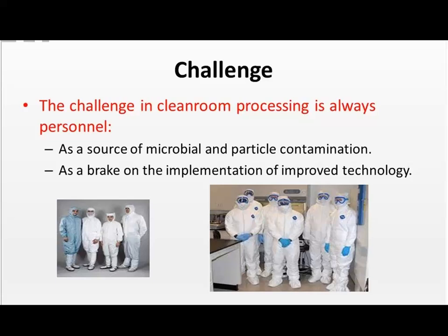When you're in an aseptic environment, movement is critical. You want to make slow, intentional movements, because every time you move, you slough off particles. You want to make sure no one is reaching inside, whether you're in a sterile or a non-sterile manufacturing suite, and that no one is opening a coverall and reaching inside. That is a source of contamination.